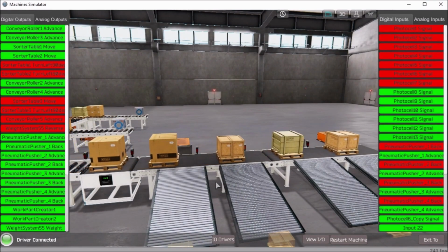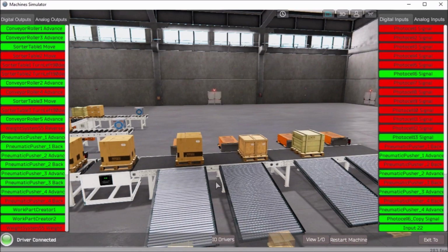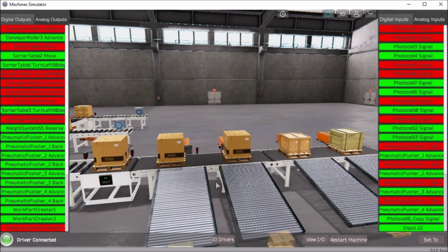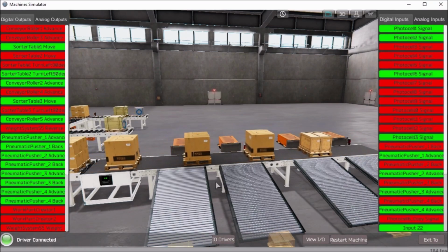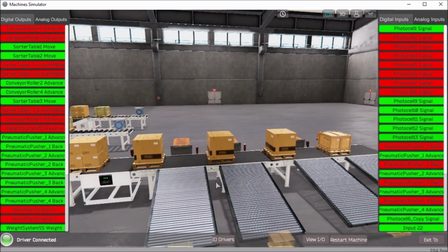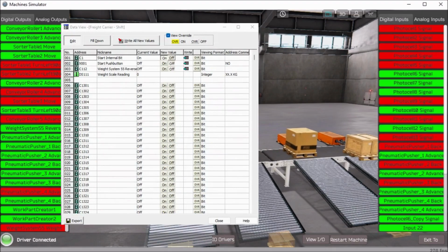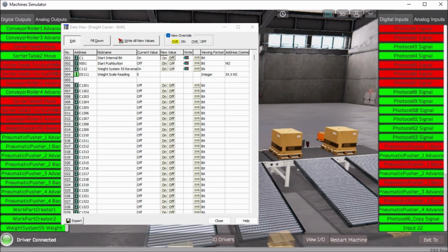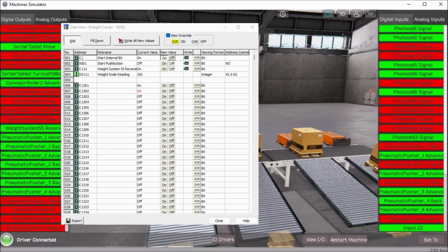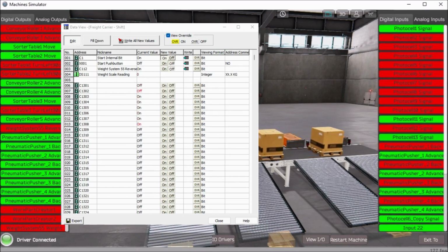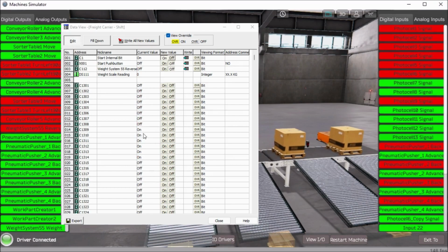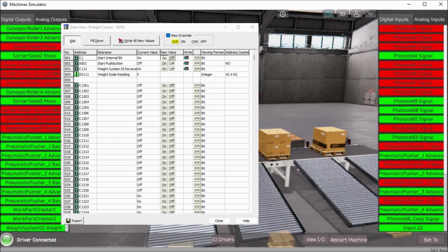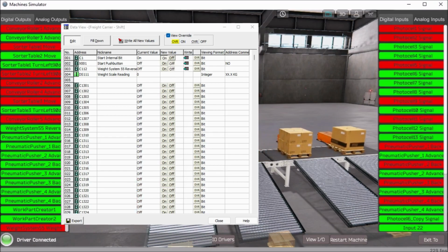So this is where we're going to troubleshoot and look at our PLC, and you can see how it's ejecting the boxes to the appropriate ramp. And this is all done with our shift register, and we can take a quick look at our actual data view. And in data view, you can see that here's my example for the bits going to the last register. So as you can see, our values, and you can see the actual box itself turning those bits on and then going down. And then finally, when it sees that light for that final eject or reject station, it'll actually fire that box onto the exit ramp.